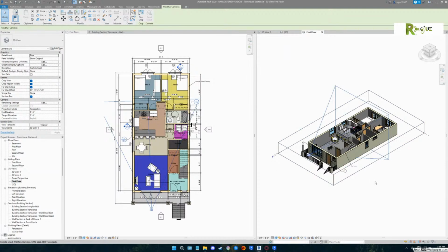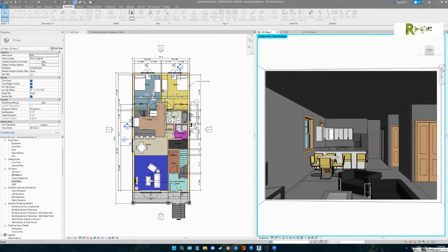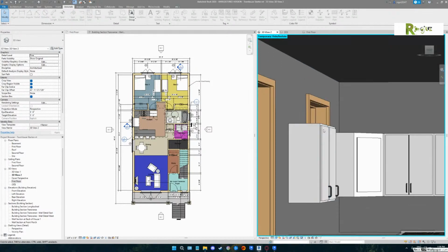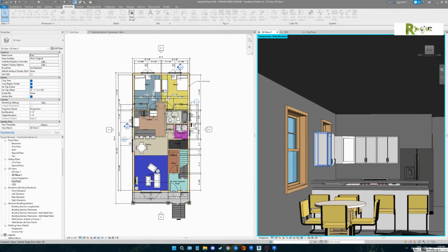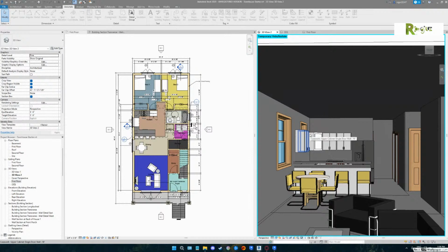All right, Nate. One of the problems I see, your window head heights and your door and your wall cabinets are not working out. Go back to that 3D kitchen view that you showed me. See where your base cabinets and wall cabinets are. See how high your kitchen windows are. That's a little bit unusual. Then it needs to come down, right? Probably the cabinets would go up, and they might even have a wall above them sometimes, because you don't want the dust to pile up.